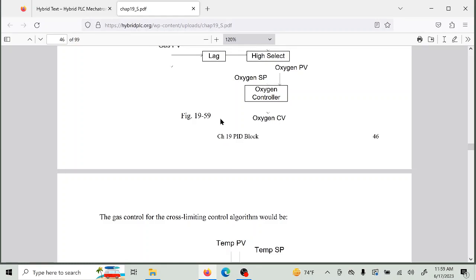Let's say you collect the information every 1/10 of a second. So every 1/10 of a second you put one in, 5 seconds later, 50 variables later, you take them out. So basically you're just lagging that signal that's coming in and going out. Picture a rail car going into a tunnel, and then 5 seconds later or 10 seconds later it's coming out the other side. That's what we have here, is a lag block that you might have to build someday.